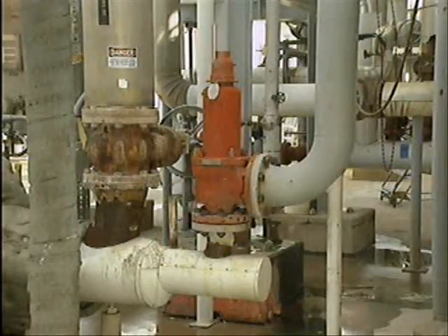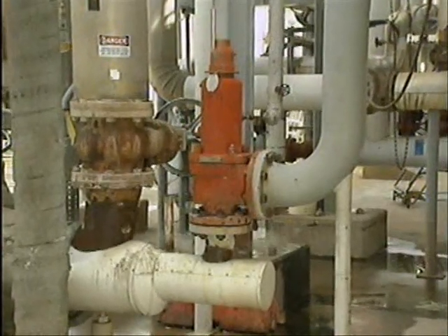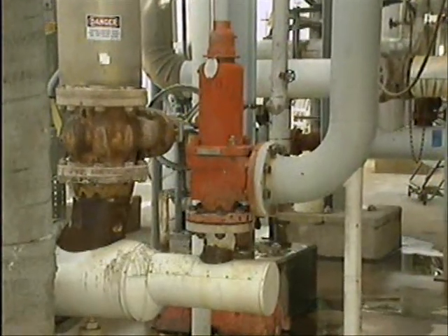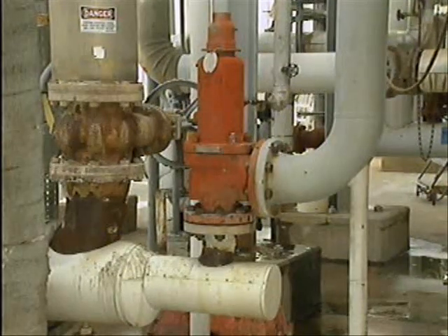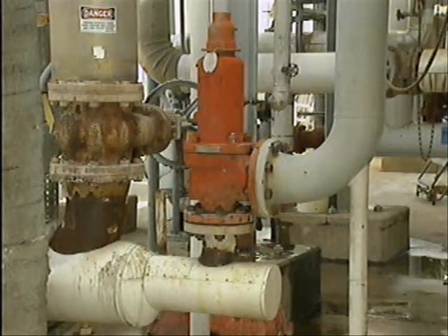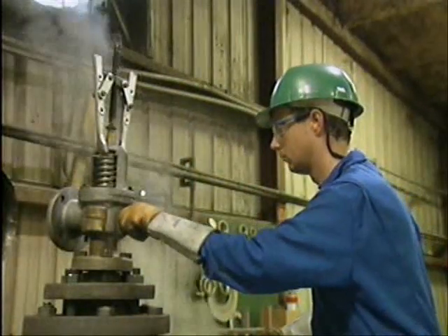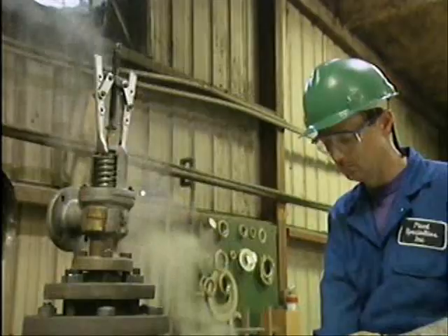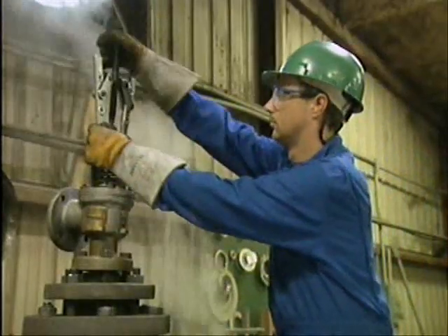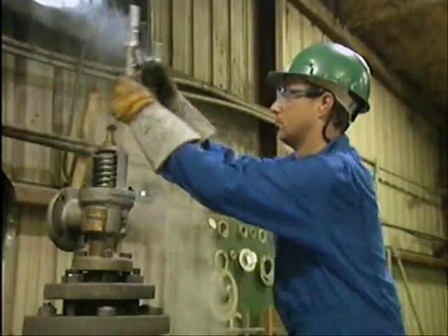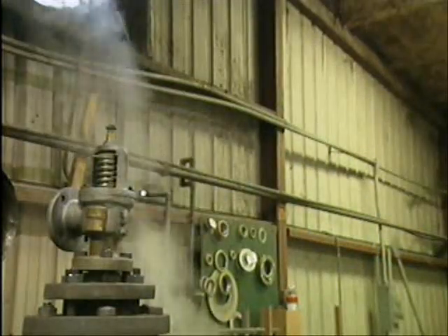Never apply a gag to a cold valve that will be heated. The valve stem expands considerably as temperature increases, and if the stem isn't free to expand, it will be bent. Never leave a gag on a safety valve during normal system operation, because a gag makes a valve inoperative, and the system or equipment that the valve is installed on will be unprotected.